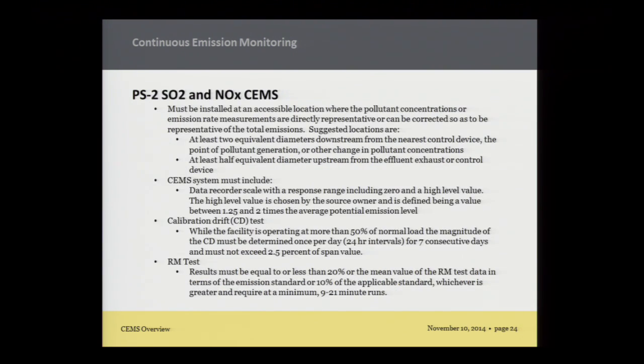So Performance Spec 2 really applies to SO2 and NOx, but it ends up pulling in everything after this Performance Spec. Pretty much points back to Performance Spec 2, except for your O2, CO2 requirements, which have a little different calibration error range, but we'll talk about that.